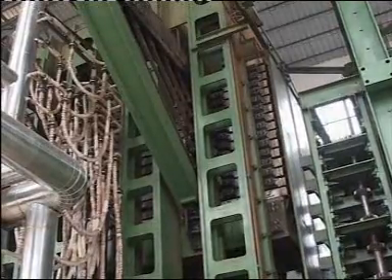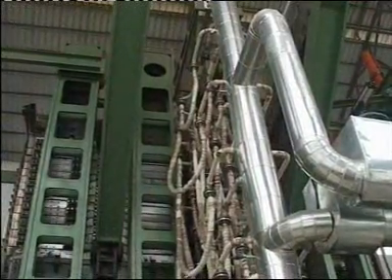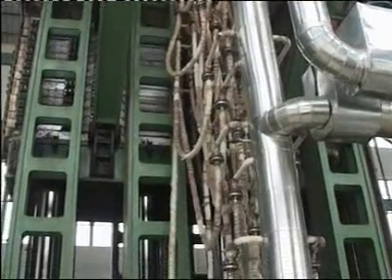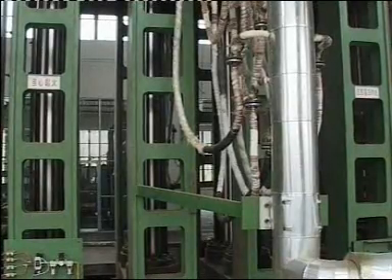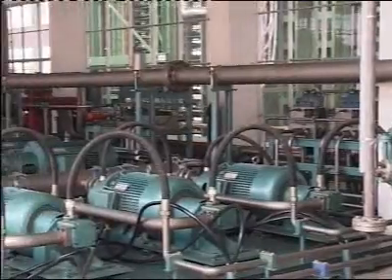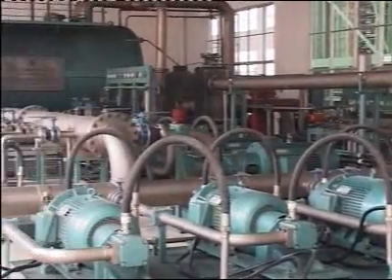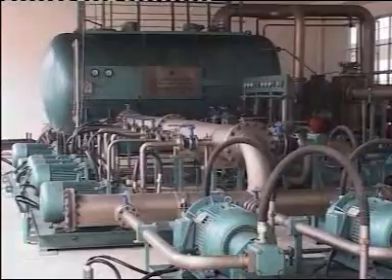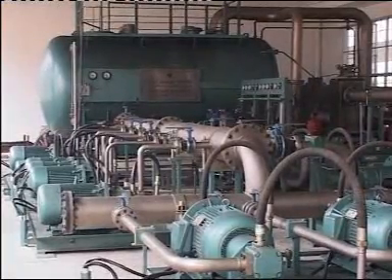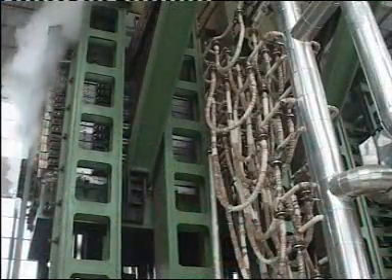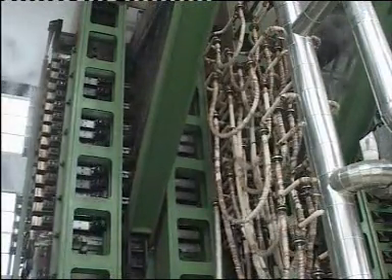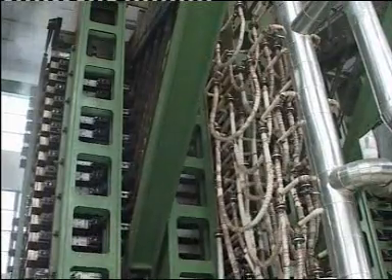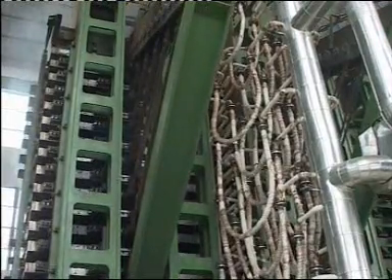The 80,000 cubic meters per year MDF production line is equipped with 4x16 15 opening hot press. The hot press is with enclosed framework and upwards welding hydraulic cylinders. Saturated steam or thermal oil can be used as heating medium. When pressing cycle is finished, the hot press will be opened automatically.